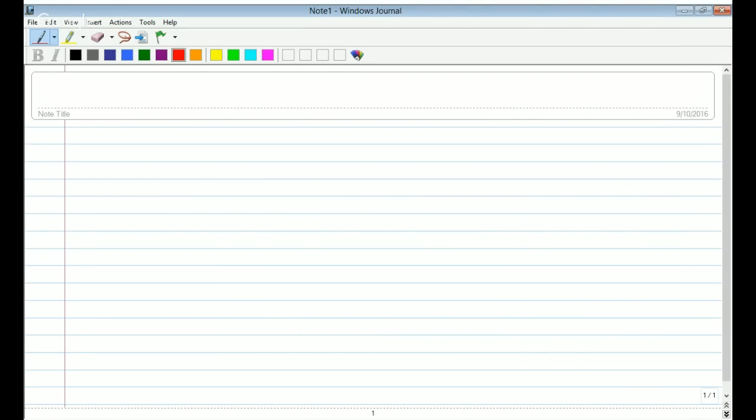The next is from Anirban Das Gupta. A 440 volt, 50 Hz, star connected alternator has rated full load current 50 ampere. RA is equal to 0. To induce rated voltage at no load, IF required is 2 ampere. When short circuited, IF needed to circulate rated current is 1.5 ampere.